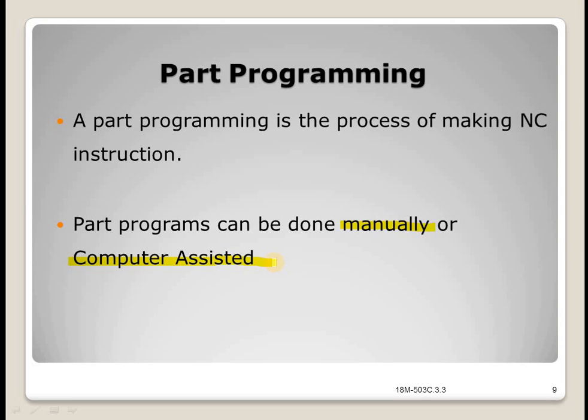While preparing a part program, you need to perform the following steps. First, determine the startup procedure, which includes the extraction of dimensional data from the part drawings and data regarding surface quality requirements on the machine component. Select the tool and determine the tool offset. Set up the zero position for the workpiece. Select the speed and rotation of the spindle. Set up the tool motions according to the profile required. Return the cutting tool to the reference point after the completion of work. End the program by stopping the spindle and coolant.